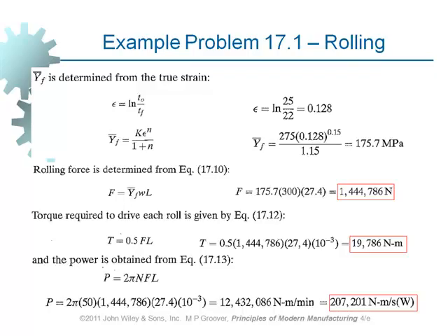If the operation is hot working, then what do we expect for the value of the strain hardening exponent? At elevated temperature above recrystallization temperature, the value of N would be equal to 0. The reason is that at elevated temperature above recrystallization temperature, the material does not become hardened after deformation. It will always have the same hardness value. Below recrystallization temperature, it gets harder and harder. So there is a value for N which is non-zero.